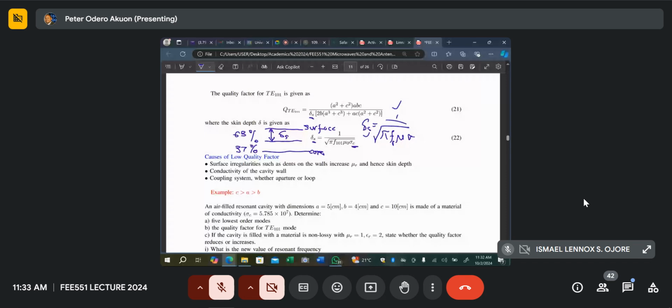Now let's see if we can get some resonant frequencies for a cavity. Here we are only using TE101, where M is 1, N is 0, and P is 1. Do you think there's a case where we could have a TE mode? 100 we know is possible for hollow. Do you think it is possible to have TE100 for a cavity?